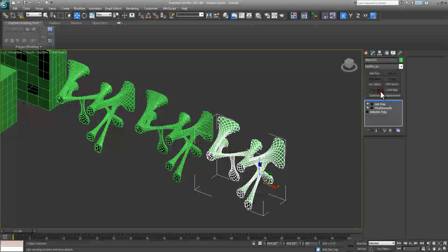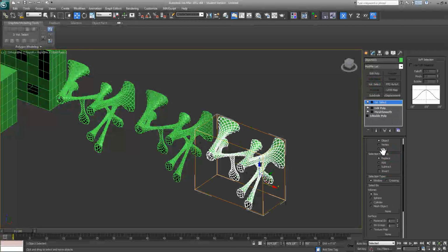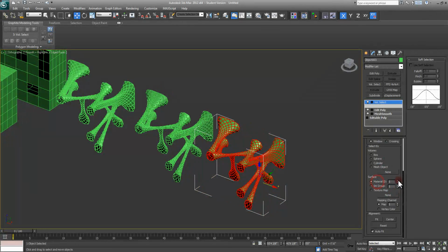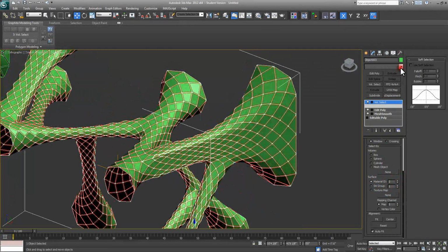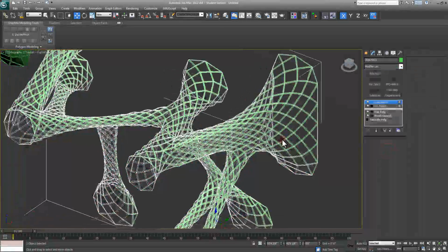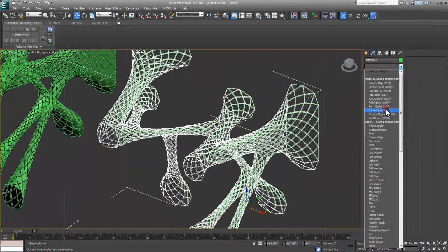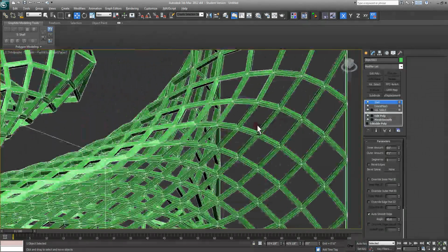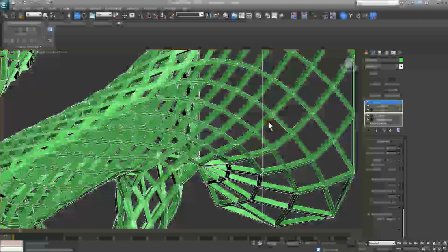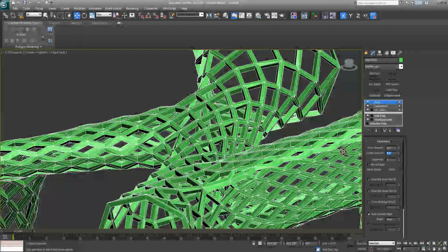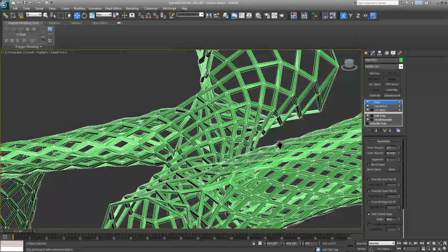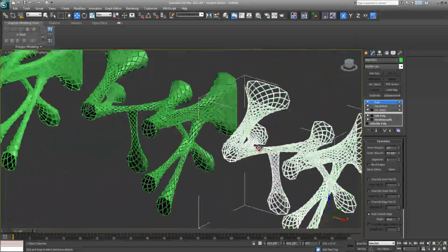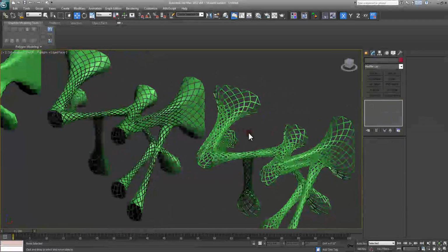And again you see that break here. I'll do a volume select by face, come down, do material ID number 2. And then I'm going to come in here and do delete mesh, and then I'm going to put a shell modifier on this just to give it a little bit of thickness. So you can see now my geometry has some thickness. Maybe that's a bit much, an inch. Again, this is all arbitrary. So maybe I do 1/2 inch, something like that, and we'll just leave the segments at 1. Now say I want these guys to line back up.